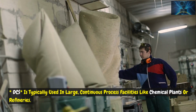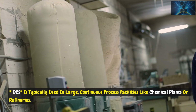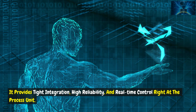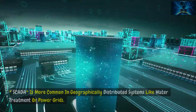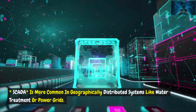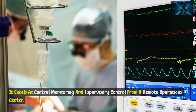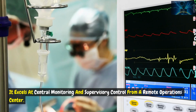DCS is typically used in large continuous process facilities like chemical plants or refineries. It provides tight integration, high reliability, and real-time control right at the process unit. SCADA is more common in geographically distributed systems like water treatment or power grids. It excels at central monitoring and supervisory control from a remote operations center.